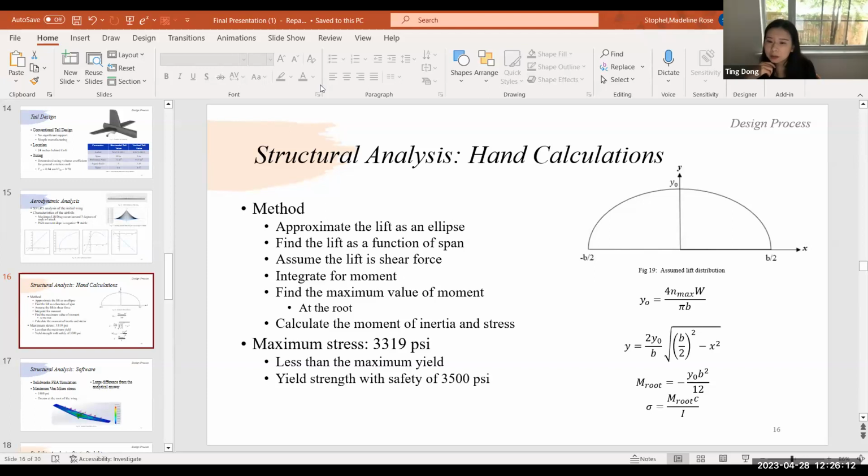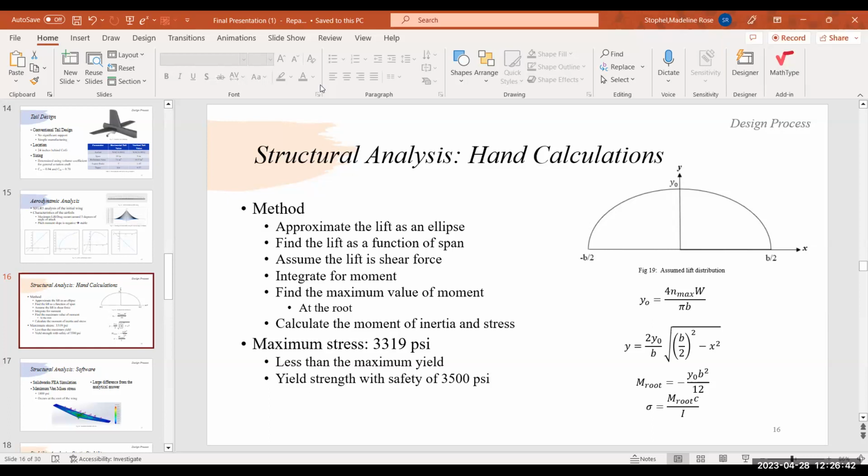Okay, that's good. Yeah, so it wasn't a combined scenario with drag and impact on the ground during landing, but we did use approximately 3.3 times the weight of the aircraft. The expected weight of the aircraft, at this point in the design phase, was approximately 4.5 pounds, is what we had estimated. Sorry to interrupt, Jacob. You can continue. Okay. Let's talk about the next slide.